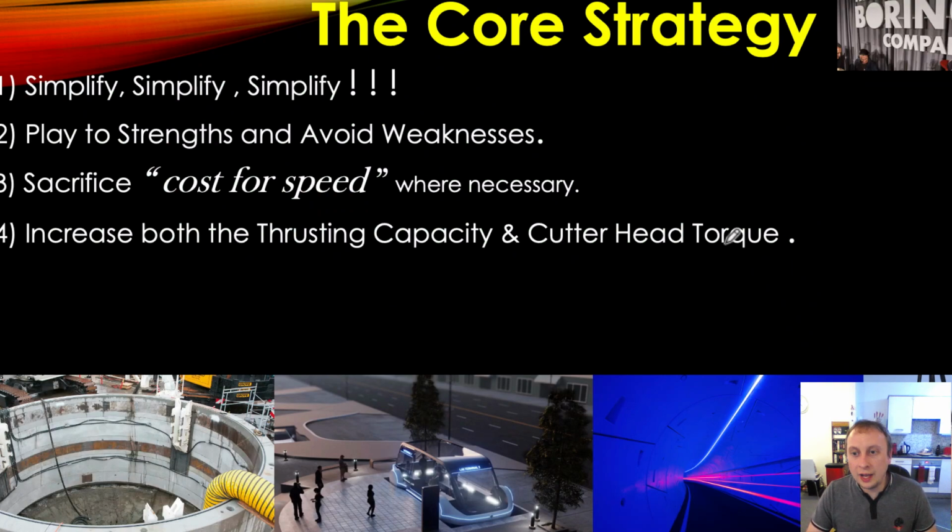In terms of the cutter head, you increase the torque of the cutter head, maybe 20%, 30%, 40%. That's all well and good, but you need to increase the thrusting capacity by maybe 100%, maybe a bit more. So the focus needs to be on the actual jacks rather than increasing the amount of electrical power that you're giving the machine, in my opinion.